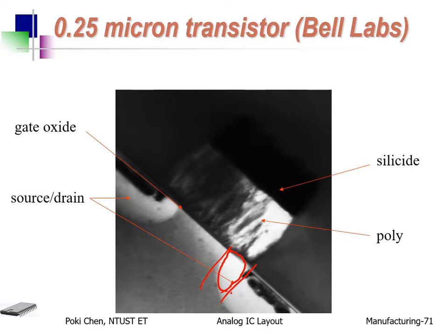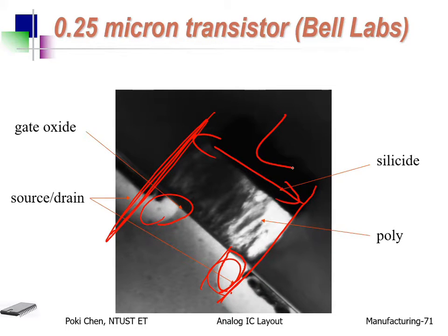Sorry for that. Okay? So you have side diffusion here, you have side diffusion there. So for the length you draw, especially for new engineers, you will think, from this edge to that edge, that is the length I draw. But after fabrication, what is the real length? Sorry, real length is from here to there. Okay? So the real length is much shorter.